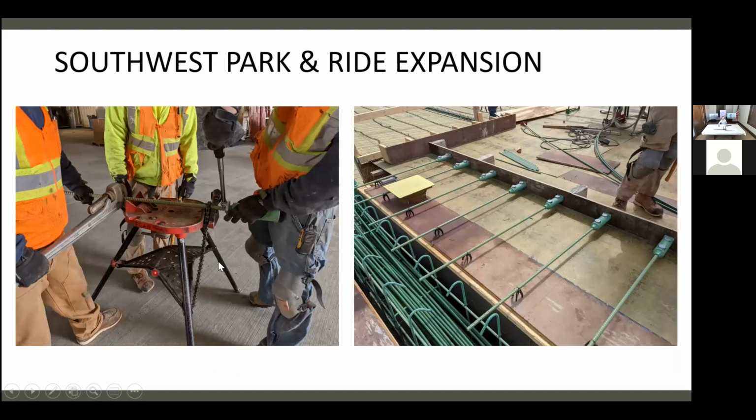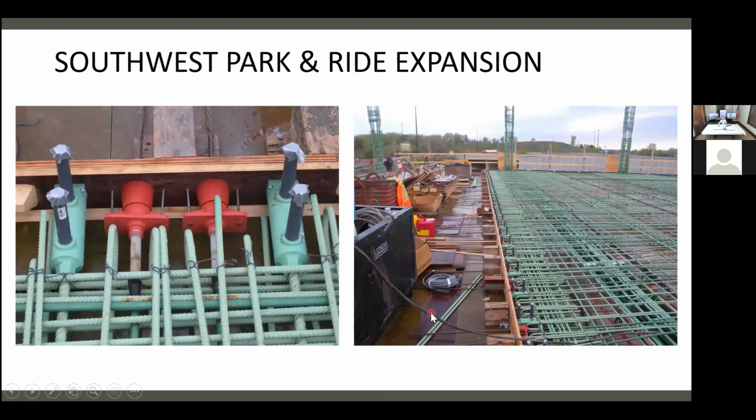So they're torquing the bar here in the first installation. Simple mid depth of the slab installation here. And this is all that additional steel. So if you've seen the lockable dowel, you've used it, if you're a contractor, look at all of this, okay? They're not little number 4s, but there's a ton of them. Look at this whole system on the right-hand side. You see all the way down. And that's both sides of the joint, okay?